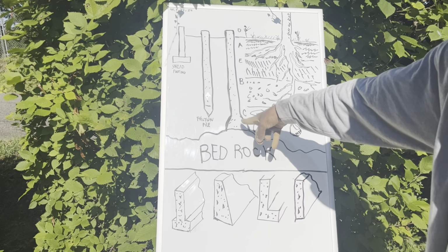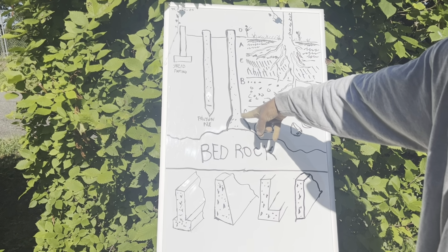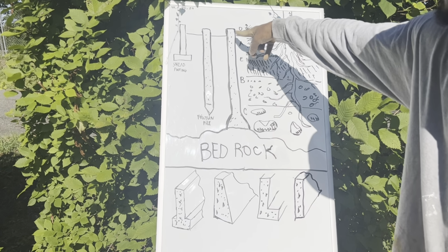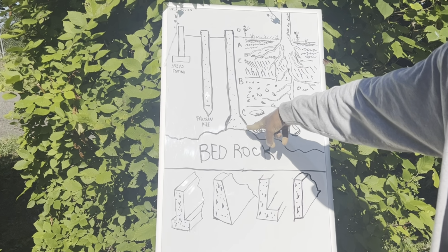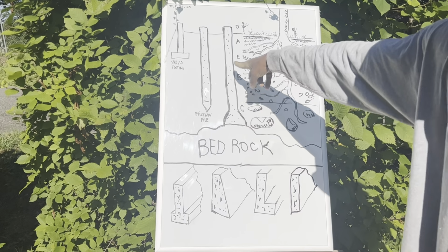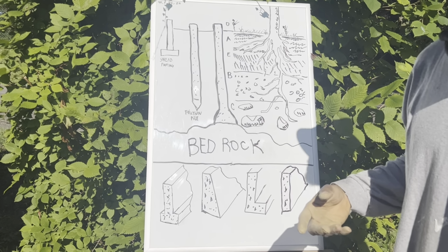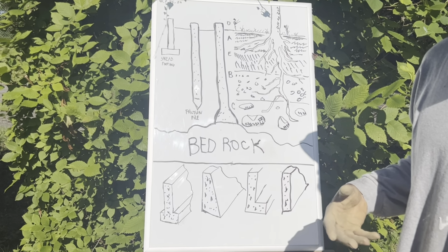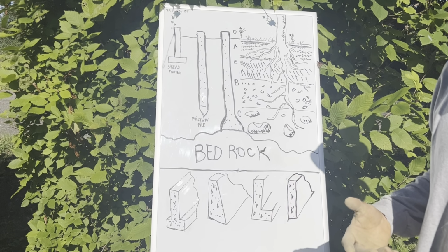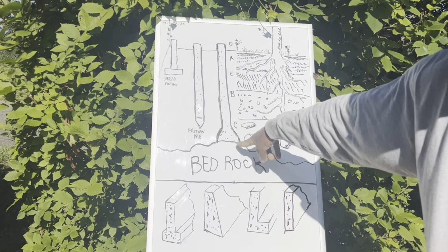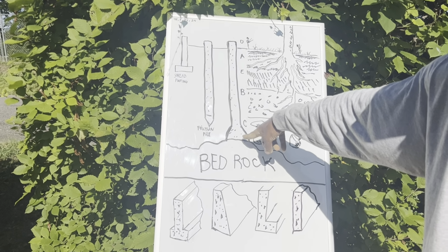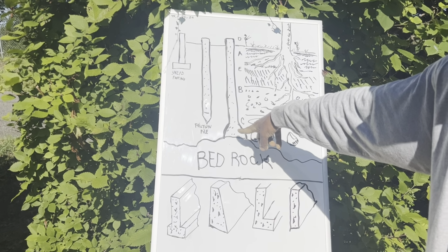And as you move on, this is a caisson. This is a caisson pile, which you see, this caisson pile is hitting bedrock. So this is going to be stable. This is something you will use maybe for a high rise, or what you would call a skyscraper, you know what I'm saying? Bigger commercial buildings, industrial buildings. You want to hit bedrock with those large buildings.